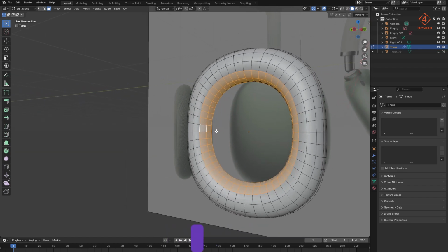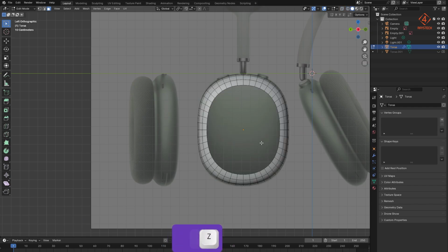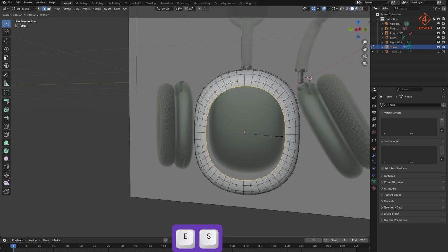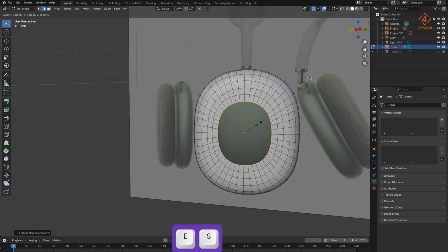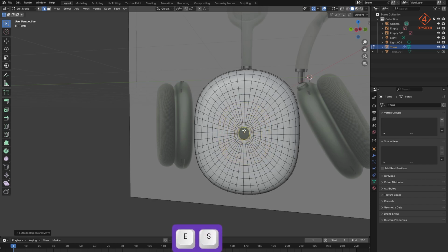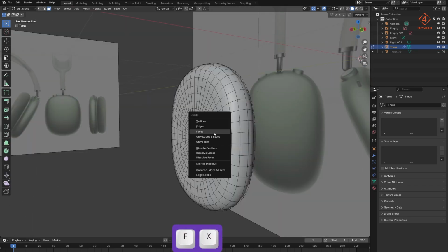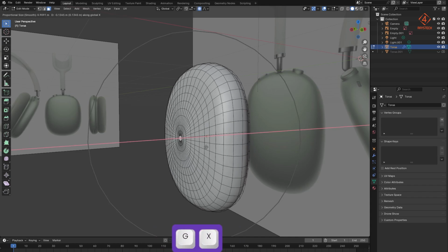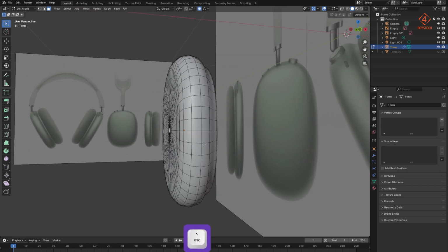Now I'm picking up these faces and I will get rid of these. I'll pick up an edge and use the same extrude and scale function to just keep making more of these loops inside, leaving a very small face in the middle, selecting that edge, pressing F to fill it up, and now we can move it out, but we'll turn on the proportional editing and then move it out. So we want to create a little bend, sort of a bump on the end.